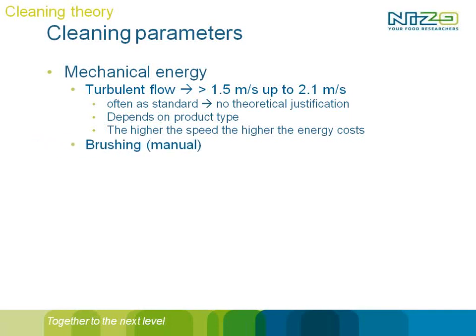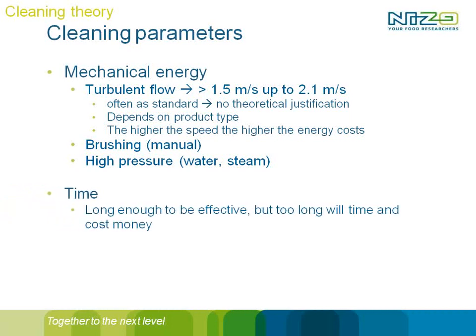Looking at manual application of cleaning, which is not really CIP, but sometimes you have to do manual cleaning. Brushing is very subjective because it depends on who's doing it, but it's possible. A third way of having mechanical energy is high pressure, mostly done to clean surfaces, ceilings, or floors. Steam can be applied, but it might be dangerous for personnel because of the high temperatures. And then finally, time. If you have enough time, of course you can wait, because time is also doing its work.